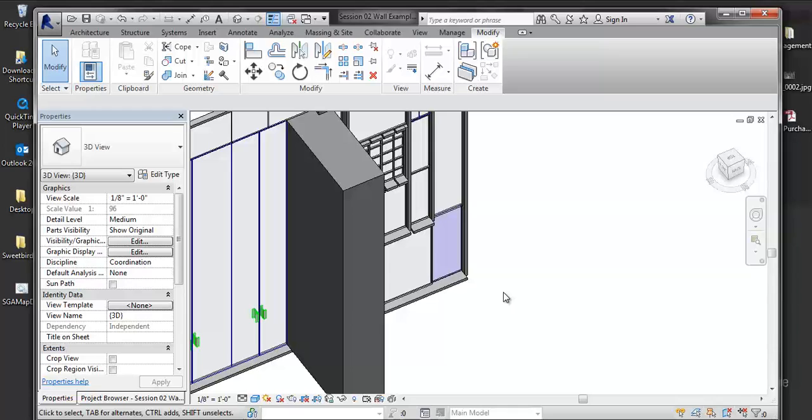There's nothing there, right? I can do a whole line of these. If I have my column coming up on the outside skin, and then I'm using a panelized system that's wrapping that column and bringing my curtain wall with it, I'm going to put a blank in it and either handle it with the column, or I can actually load a panel that's acting as a column into my curtain system, which I've done also. In terms of scheduling it, there are trade-offs for everything we do. Just be aware of it. We had to eventually switch those out and put real columns, but up until DD, that was fine.